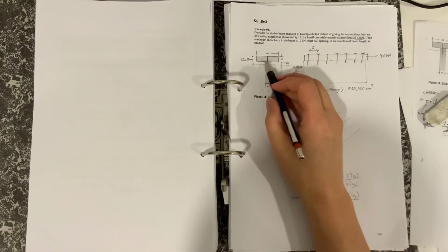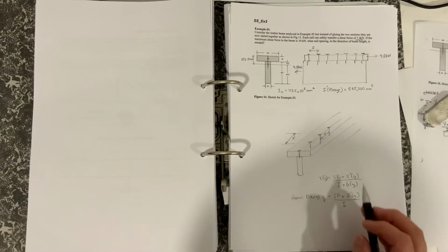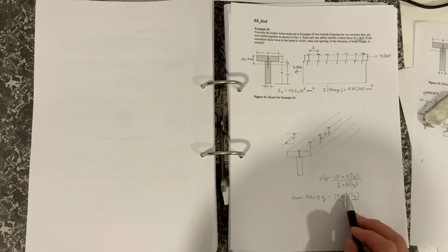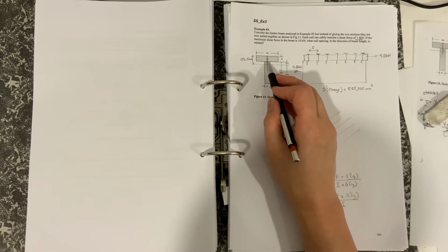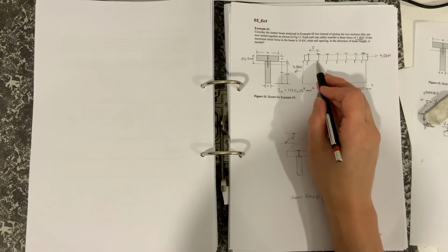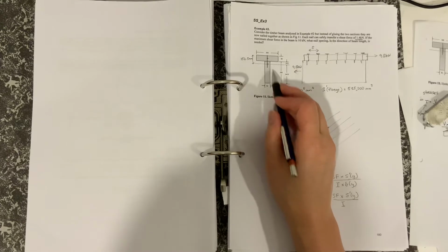Okay, so we've got our S dash, both for the stress, so that this equation is to work out the stress at any point, and this equation is to work out the flow. So we want to know the flow at that point there, because that's where the nail would be sheared, because you've got two planes, of course, which are moving in opposite directions.